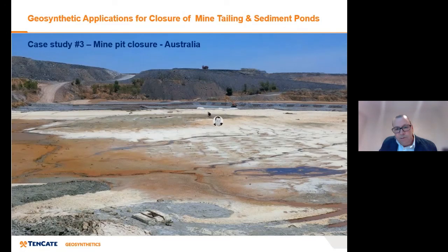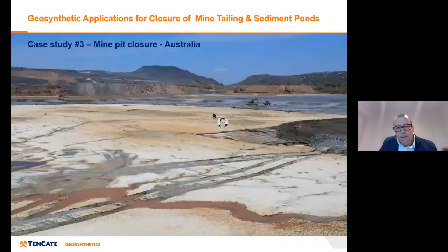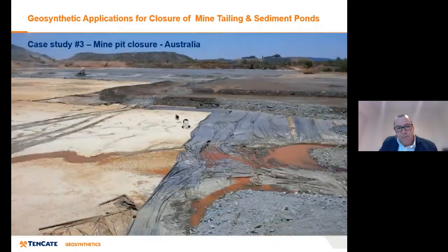So they're putting the reinforcement layer down and slowly working their way across. You can see here the reinforcement layer just building across. A little bit of a closer photo. They had multiple layers of geosynthetics. The black layer here is just a cheap slick film woven on top of the PT 150 kilonewton biaxial reinforcement layer.